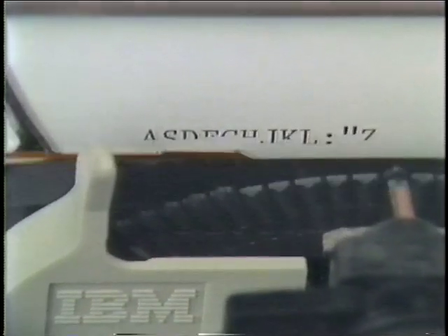This may appear as partial characters or no print. To correct this, turn the machine off, then back on. The machine will re-home the ribbon lift cam during the POR. Once the ribbon lift cam re-homes, the print should be good again.